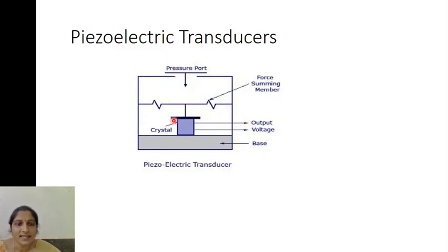Now the construction diagram of this piezoelectric transducer will be like this. This is a complete case. On the top of this case, you are provided with a port, the pressure port, on which you can apply the pressure. Under that you have the summation member, and under that you have a Rochelle salt